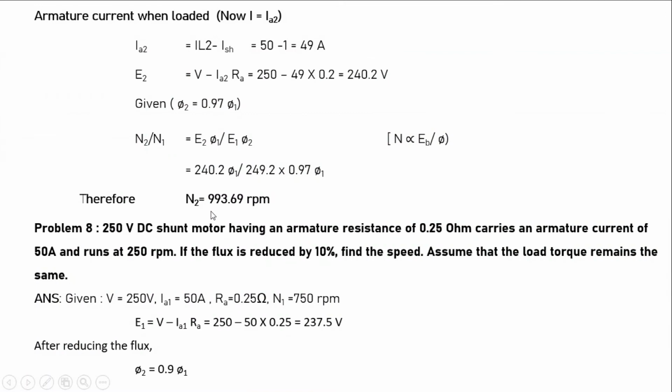Once you get N as 289.5 rpm, you can substitute here. Shaft torque is given by 9.55 into output by N, 9.55 into 8.2 into 10 raised to 3 divided by 289.5, and we will get 270.5 Newton meter.